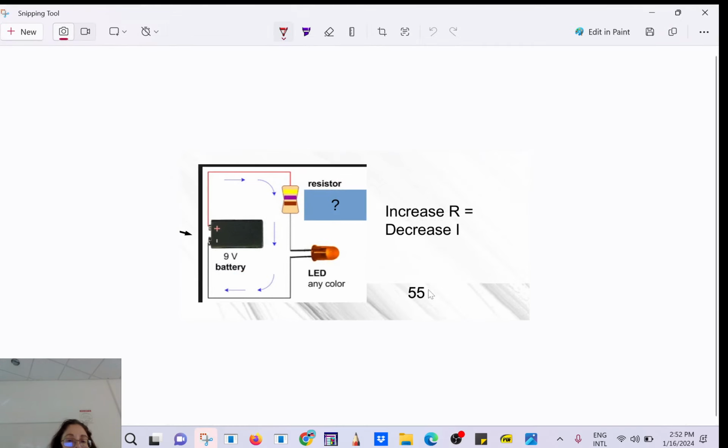So it needs a minimum of 1.7 volts. Yes, it's a red LED. It won't work unless you provide 1.7 volt. So if you take a 1.5 battery, for example, the LED will not light because it doesn't get 1.7. It has to do with quantum physics. It needs a gap of 1.7, otherwise it says no way.